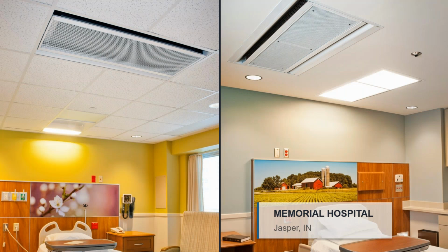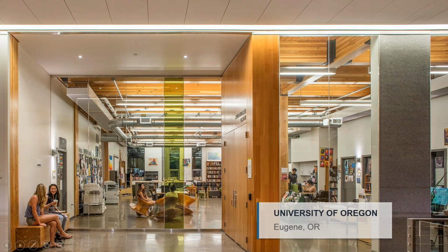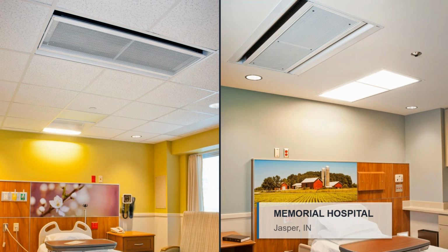So next up are the chill beams in a hospital that we wanted to show. On the left is a standard ACBL for just a normal patient-style acute care space, and on the right, in most hospitals there's a psychiatric or behavioral wing typically, and so we've got our security beam installed up in the ceiling, and you can see even the hard lid style of ceiling. But the fasteners here are tamper-proof, and they require a special tool to remove the face and get access to the coil.